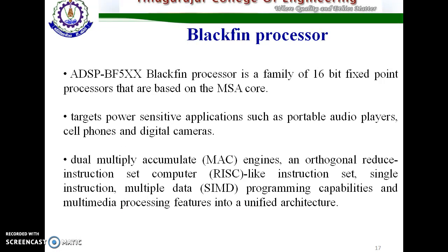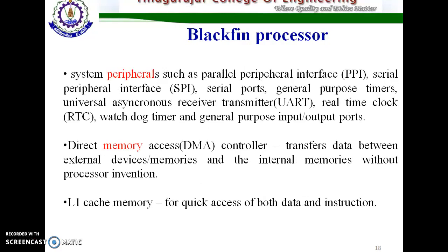ADSP is the Analog Devices DSP Blackfin processor. The Blackfin processor is a 16-bit fixed point processor based on the micro-signal architecture. It has features like dual multiply accumulate engines, an orthogonal reduced instruction set computer like instruction set, and SIMD, that is single instruction multiple data programming capabilities, and multimedia processing features in a unified architecture.